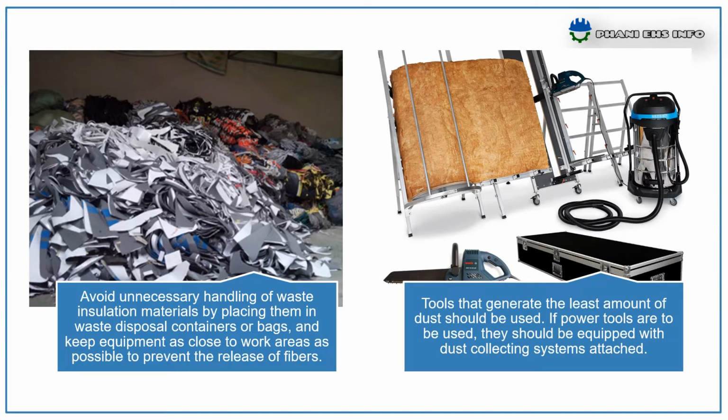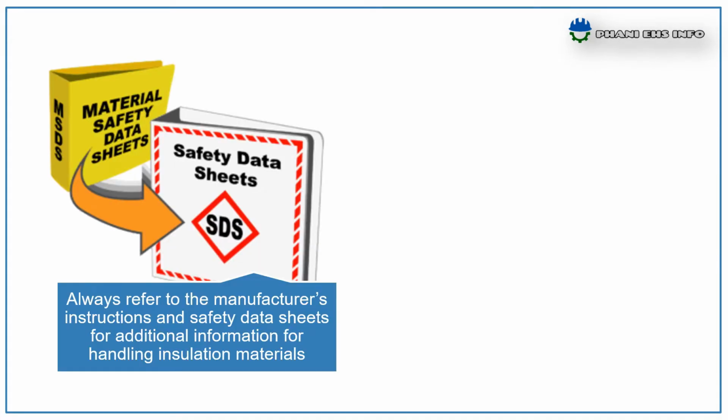Next one, tools that generate the least amount of dust should be used. If power tools are to be used, they should be equipped with the dust collecting systems attached. Always refer to the manufacturer's instructions, safety data sheets for additional information for handling insulation materials.